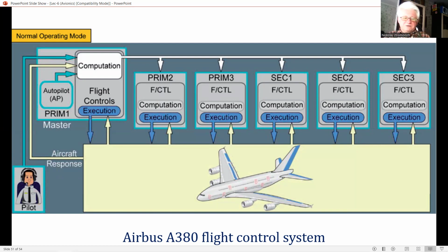Flight control protection, like load factor, angle of attack, speed, and attitude, is also part of the flight control laws and provides the pilot with instinctive procedures to get maximum aircraft performance in emergency situations. Aircraft feedback is provided by the Air Data Inertial Reference System, ADIRS, and dedicated sensors, accelerometers, rate gyros, etc.